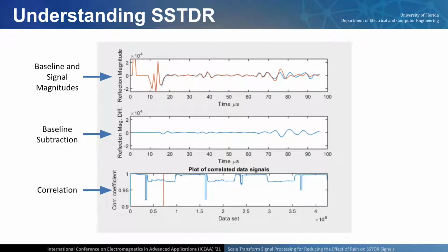On the bottom, we simply show the correlation between the two signals. A very high correlation close to 1 typically corresponds to some daylight, whereas that moderate dip that you see corresponds to nighttime. Any larger dip, such as the 3 or 4 that you can see in this problem, correspond to actual faults. One coming up right now, as you can see. So baseline subtraction is our go-to when we're talking about detecting and locating these faults.